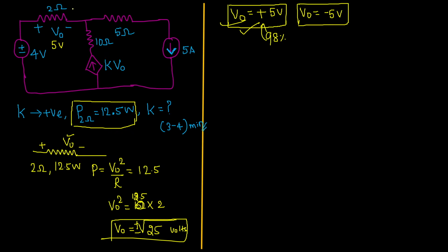Okay sir, can you please tell me in which direction current is flowing through this 2 ohm resistor? Sir, we know resistor is a passive element. There are two cases. One is, if the direction of current is given, we can find the polarity from it; if the polarity is given, we can find the current from it. So there are two cases. Let us see. In the first case, since resistor is a passive element, current entering point should be plus, leaving point is minus. That is how we are identifying the polarity when current is given.